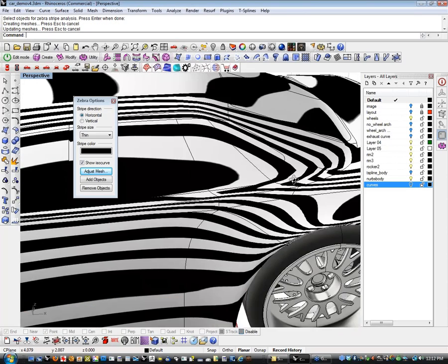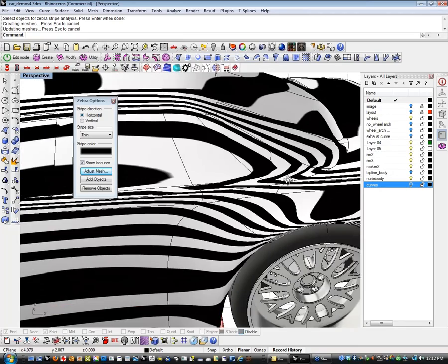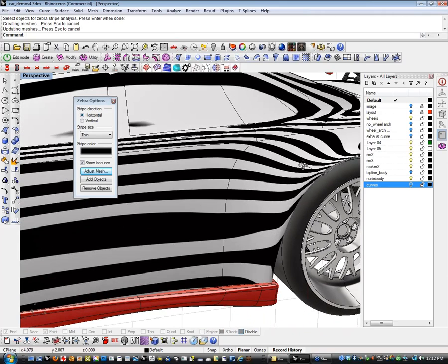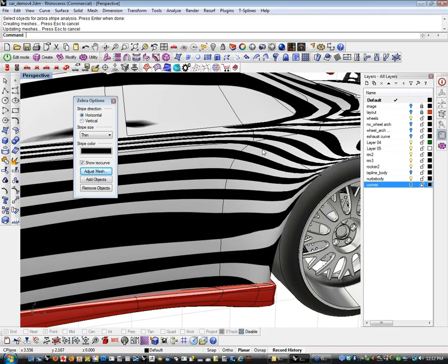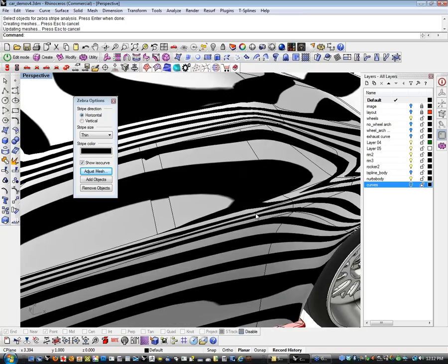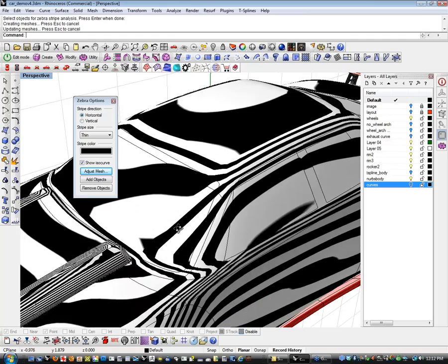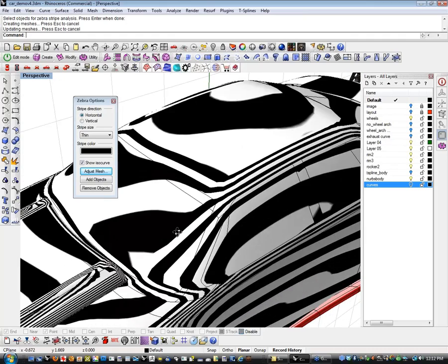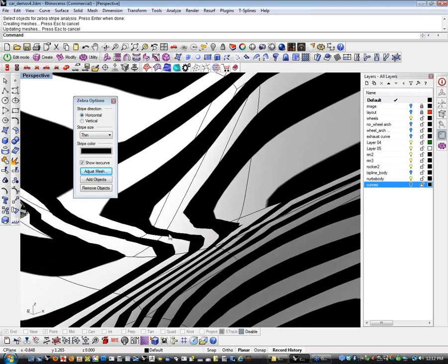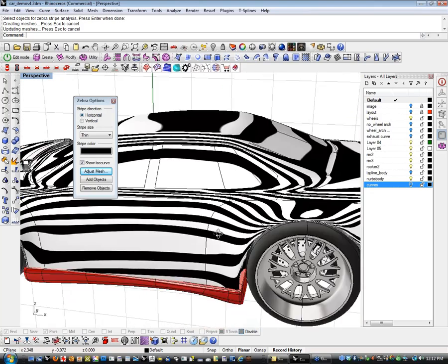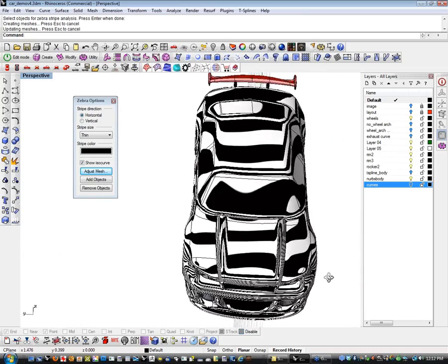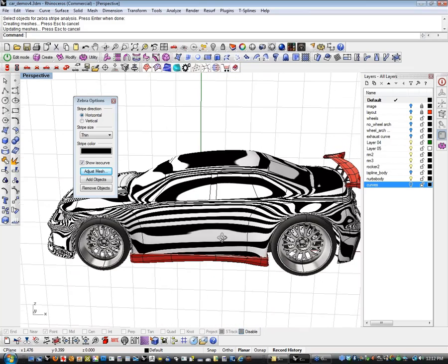That we're getting really nice zebra transitions in and out of here. This is what you want. This is a smiley face Class A modeling situation, where you get really nice highlight lines running in and out of your transitions. And again, my mesh is a little janky, which is why you're seeing the lines. But you're noticing here that they're unbroken and nice and smooth and transitioning from one surface into the other. That's what you're looking for there.